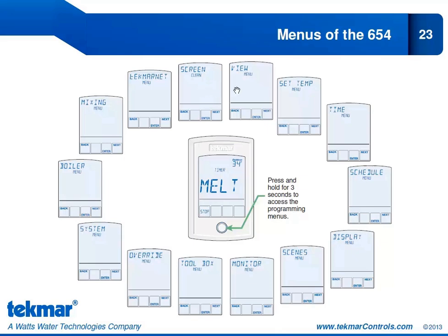Now we're going to go into discussion of most of these menus. Some of them I will not cover. I think the Time menu, the Schedule menu, Display menu, and Scenes menu are all pretty basic. If you have configured any of the TechMart thermostats or controls and you're familiar with these menus, we won't go into them in this training webinar. Just like our Designer Series thermostats, you can navigate through the different menus by pressing and holding this button for 3 seconds, and you can scroll through the list of menus by hitting the next button key.